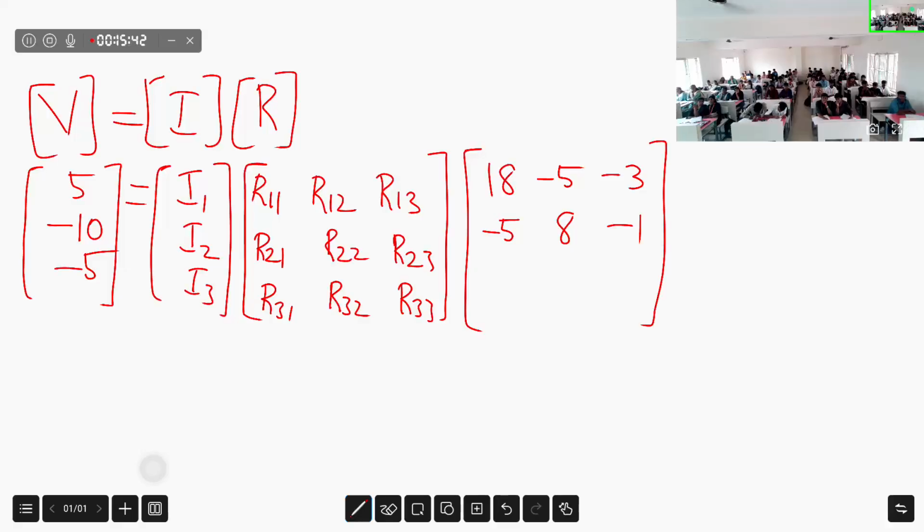So this is my matrix value. Right? The remaining procedures are the same as the given node analysis. Now what should we do? Just find out the del value. See what del value comes. How to find out the del value? It is the determinant of this matrix. Okay? Then del 1 by del is equal to I1.